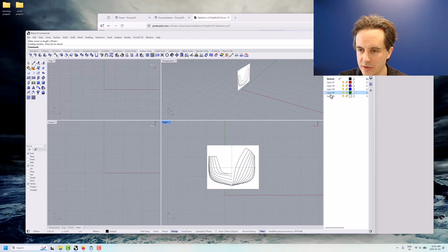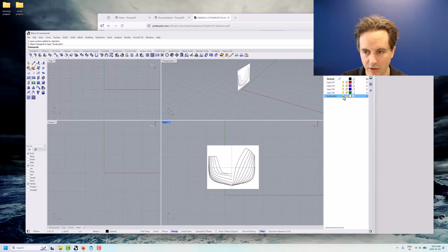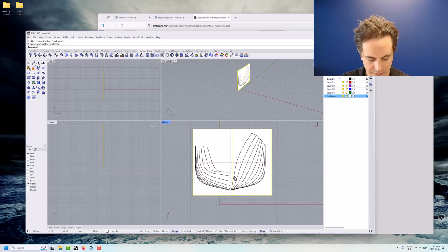I might recommend you make use of your layers. So we've got this active layer now just by clicking the checkbox here. Let's make sure the image is actually in there. So we select the image, right click, and go change object layer. This is nice because we go back to another layer, and later we can turn that on and off really easily, right? Okay, so we've put the image in here. The big thing we need to do first is make sure it's the right scale, right? So what did it actually turn out to be?